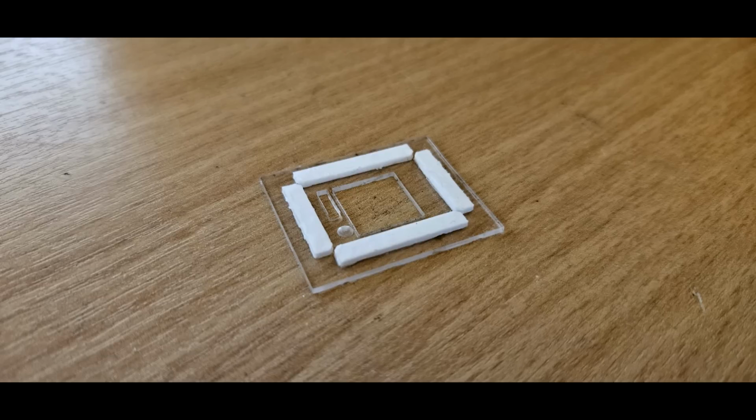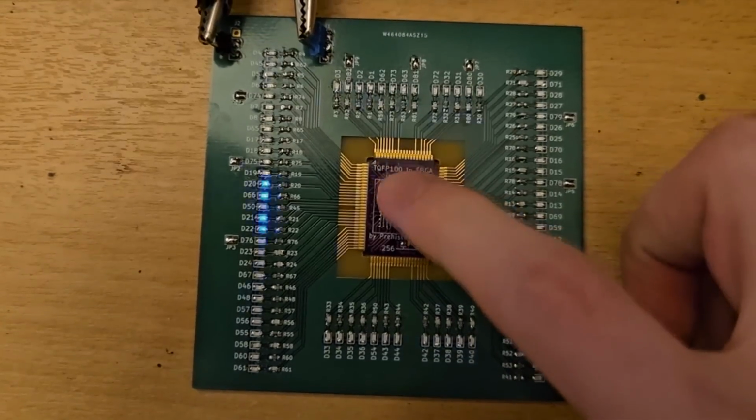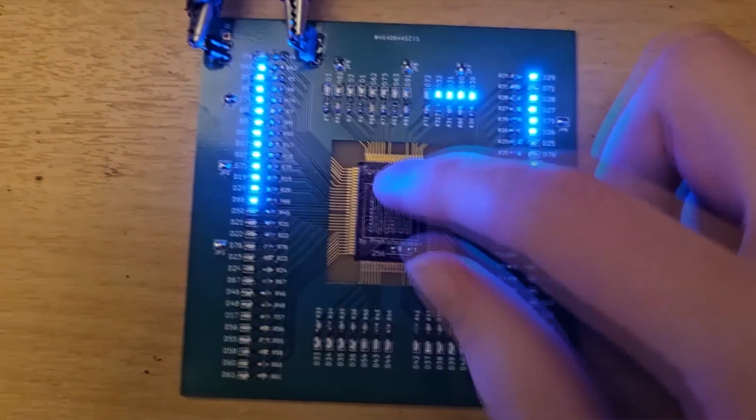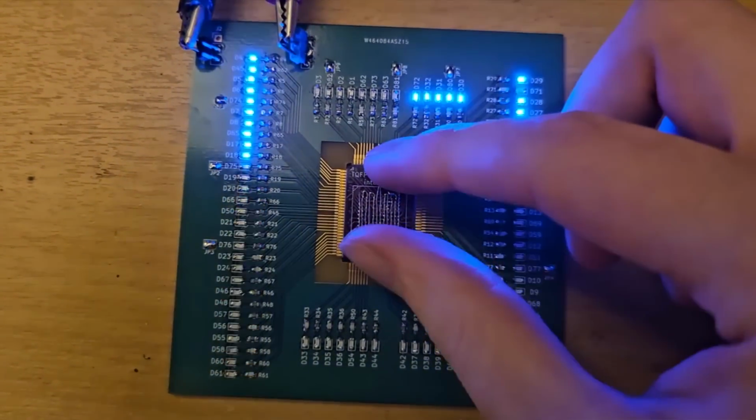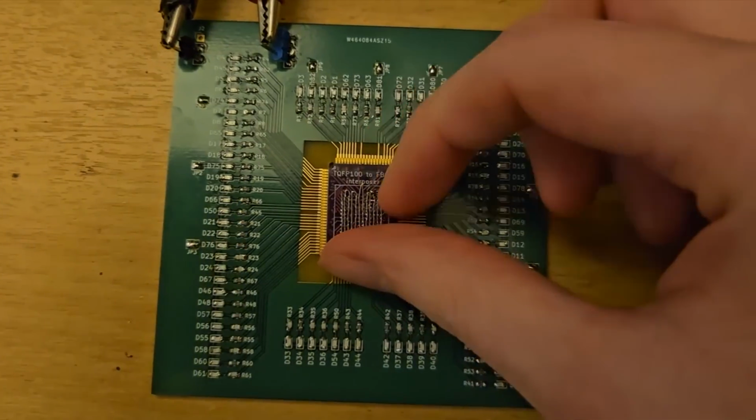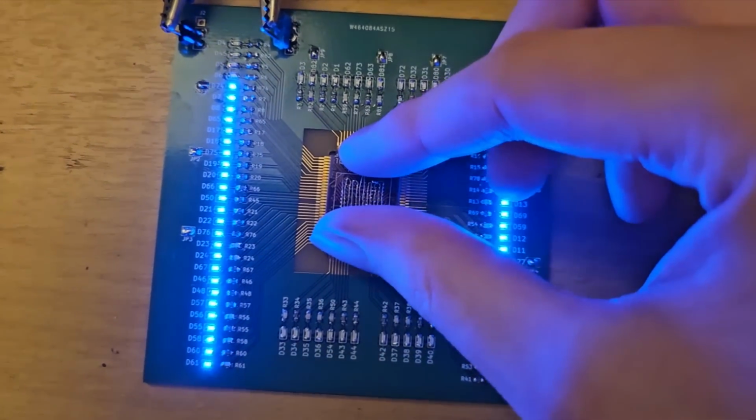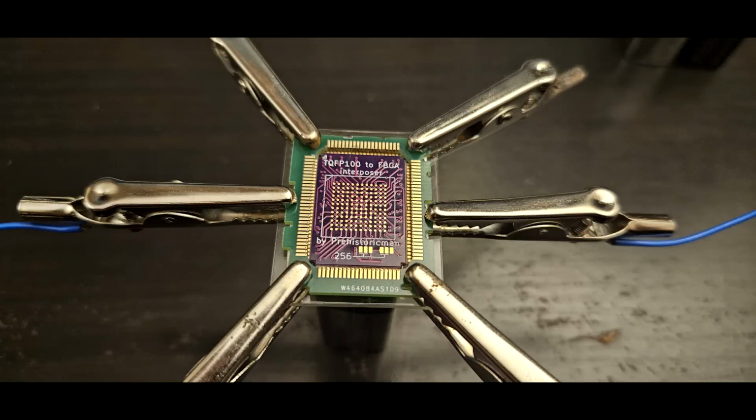So what I decided to do is do a little bit of debugging. I built this PCB that lets me see when there is contact being made. Here I'm just playing around with it, but you can see how difficult it is to get all the LEDs lit at once. I also did some single pin debugging with this solution. Even those 6 points of contact didn't provide an even contact around the whole device.